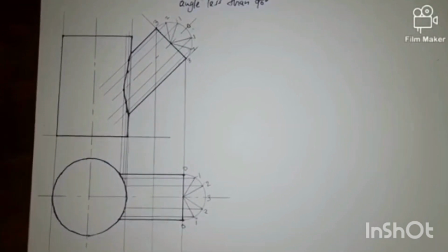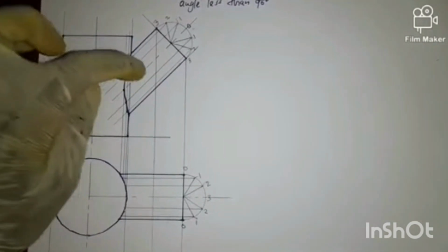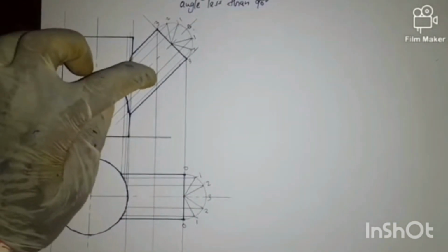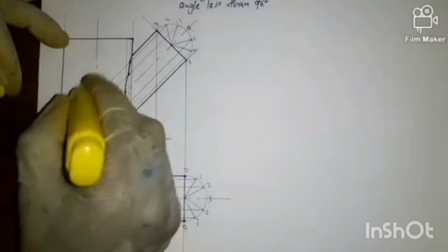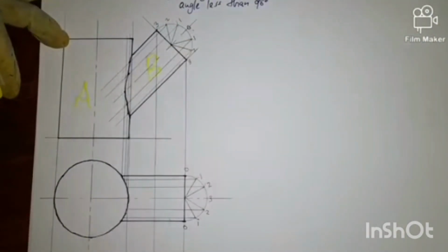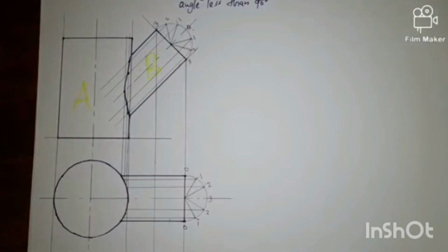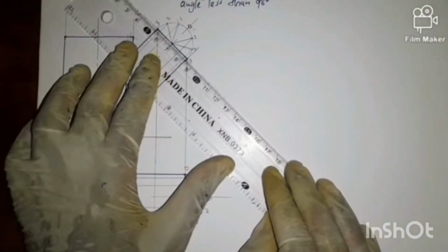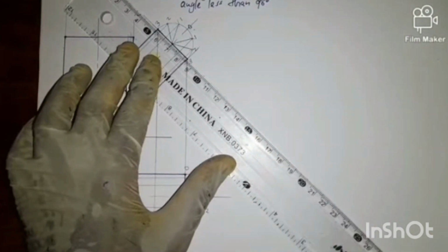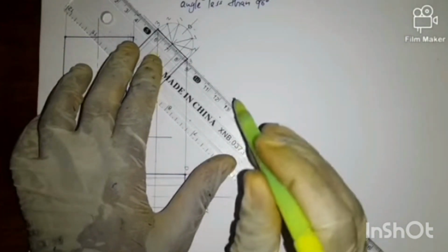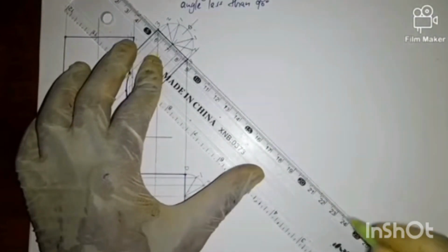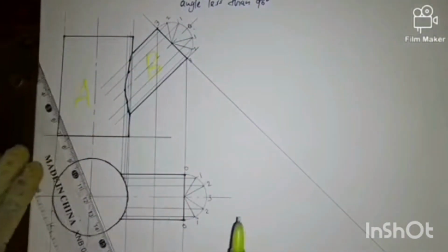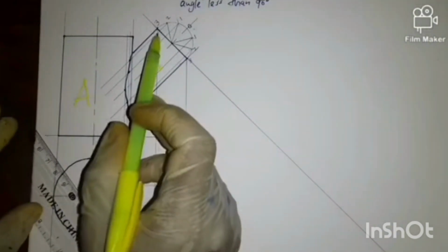So what we have gotten is the full plan and the full front elevation having a curve of intersection. We are remaining with the development of this other cylinder. We said this is cylinder A and this is now B. So how do we get the development of cylinder B? First of all, we extend this baseline, and we open it up at a point, we can say 0.3. So we draw that baseline.